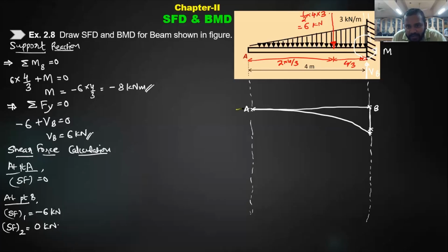At point A, the tangent is almost horizontal, so slope is 0. Therefore, see here the intensity is 0 here. The intensity is going to be maximum at this particular point. If I draw a tangent to this, it will have maximum inclination with the horizontal. So the maximum value of shear force we are having at that point. Okay. Have you understood this? So we will name this a parabolic curve because we know the curve is parabolic. So this is the SFD, that is shear force diagram.